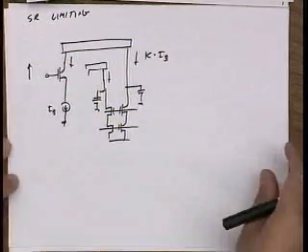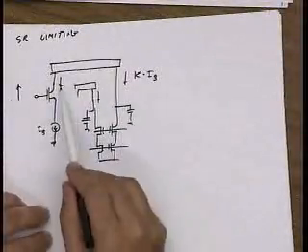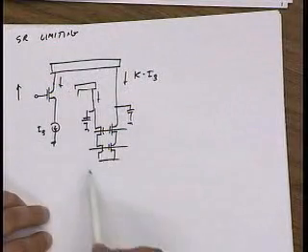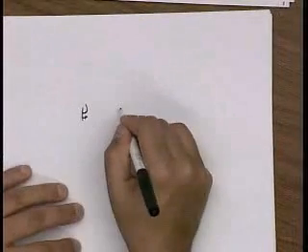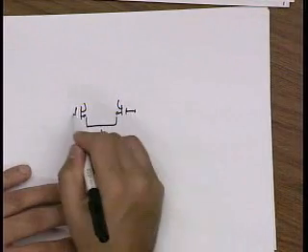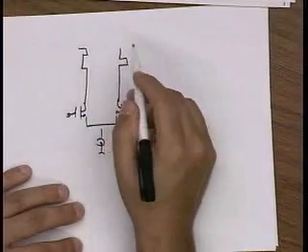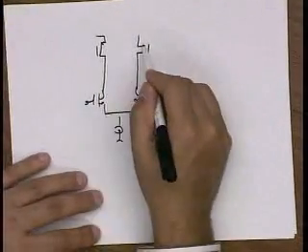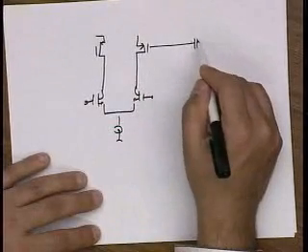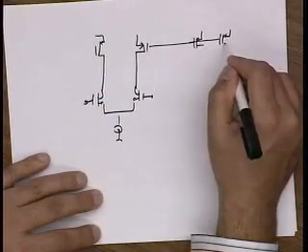So to fix that problem, I just have to add some more current mirrors, right? So what I'd like to do is to take this current, mirror it twice, and flow it over here. So here's a way of doing that. These circuits get fun to draw. So lots of current mirrors. This is why people ended up inventing a symbol for the current mirror, but I just don't like the symbol, so I don't use it. And I like the rectangle, but it's not that elegant.